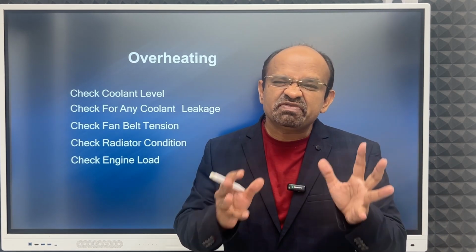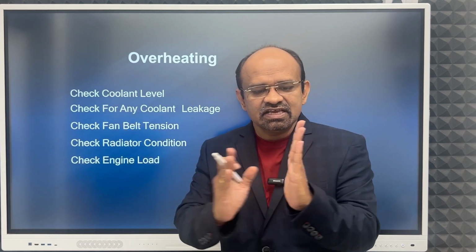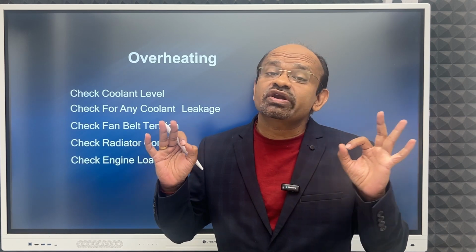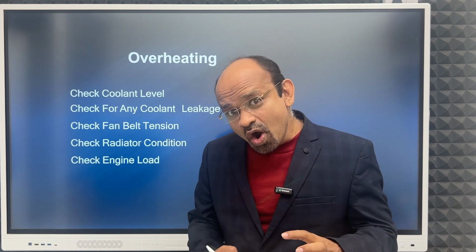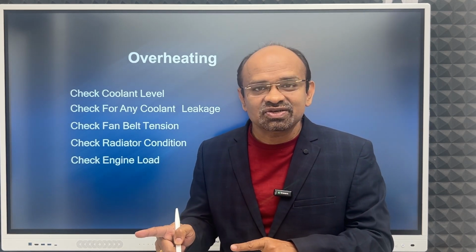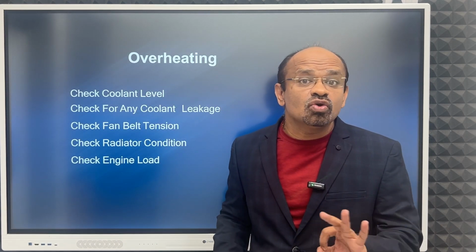Then check the radiator condition. That is another problem. If your radiator is dirty, with a lot of dirt in between the fins, and we have seen the fins increase the surface area, then the rate of evaporation or heat exchange will go down and your engine will heat up. We have seen the temperature goes up to 90 to 100 degrees Celsius, and if you don't take that heat out, it will melt your engine or other parts. Heat will keep mounting up until the parts start melting and it will damage your engine forever. So that is why check the radiator condition. These things are very, very important. Don't overlook them.